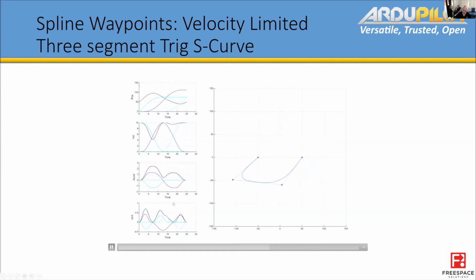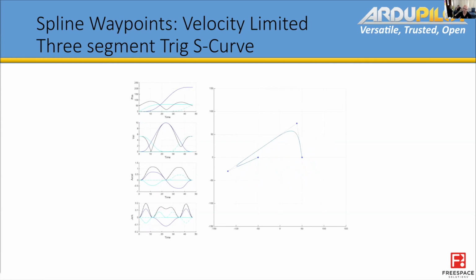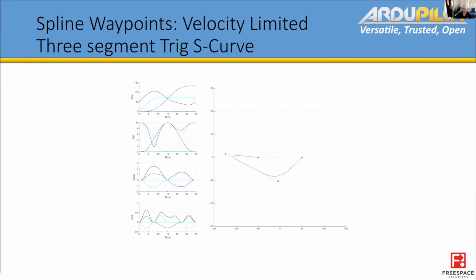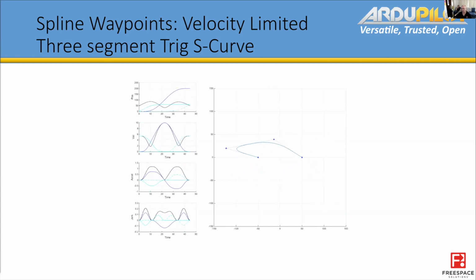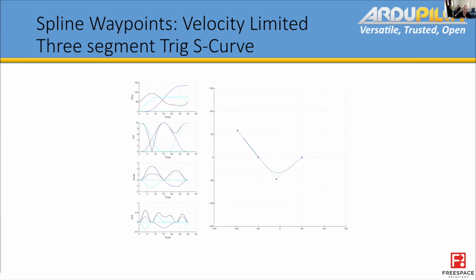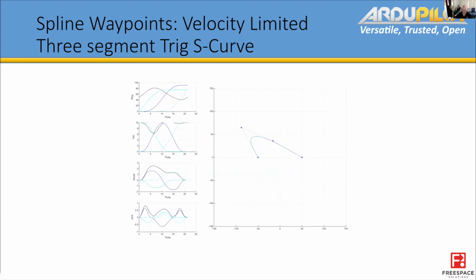Now, this isn't completely optimal, but because at every single point on this line we know exactly what position, velocity, acceleration, jerk, and jounce is, we're able to further optimize with a look-ahead algorithm moving forwards if we want to get the absolute best performance along that segment.